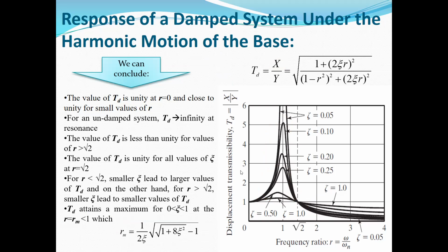Okay, so the application of these types of graphs is when you want to design a vibrating system for a real problem in experience. So you can use these graphs and find your preference, and according to your preference, you can find the suitable area for your system, and then you can design the different values, for example, the stiffness, the mass, and the damping constant for your system.